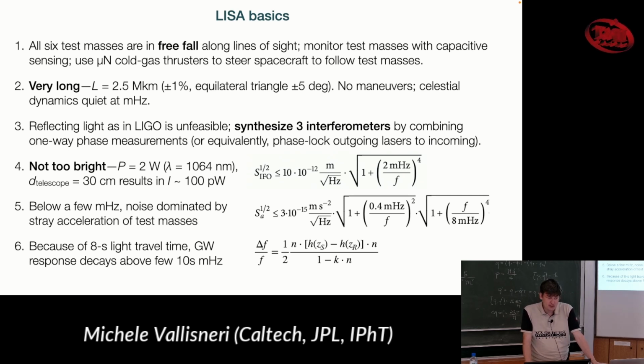So for that reason, if you don't need a lot of thrust, and in this case you don't want it, you want just a millionth of a Newton, that's a good choice. And if you see all these CubeSats, very small satellites that are launched cheaply with little power, if they have thrusters, they tend to have cold gas thrusters because they're simple, just a valve.